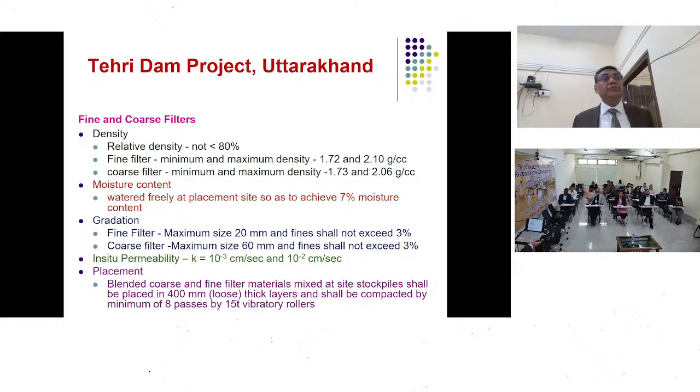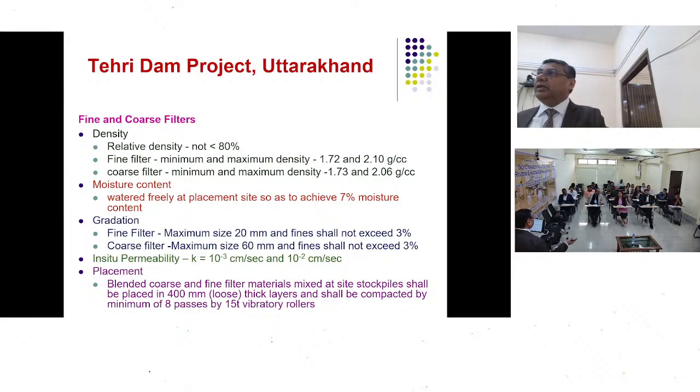Now how was watering being done? For the clay core, as I was saying, the moisture content in the borrow area was known, then the moisture content in the stockpile was calculated, and from there the quantity of material which can be carried in a particular truck was known. Accordingly, the quantity of water to be put into the truck carrying your material was calculated.